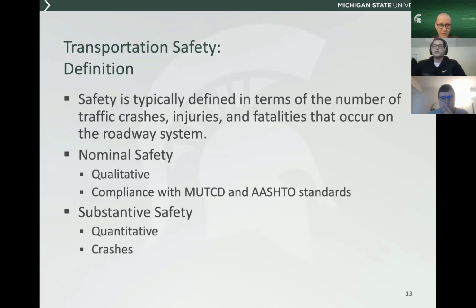But let's say we've got 60 feet of roadway available. We could compare from a safety standpoint, if we varied the number of lanes and the widths of those lanes and the widths of the shoulders, we could basically determine what the trade-offs are, at least at some level of detail from safety research based on those factors.